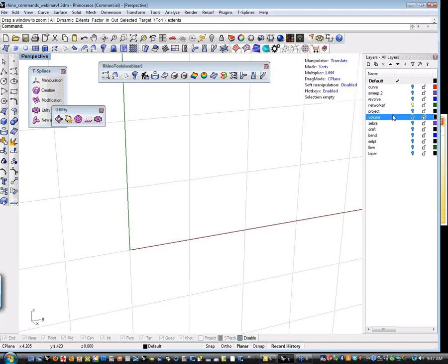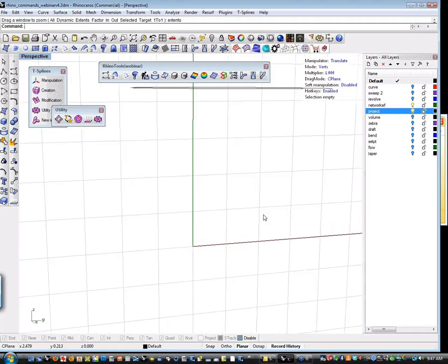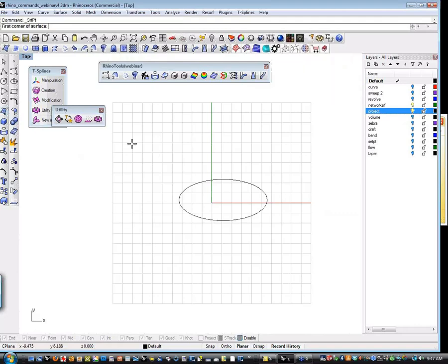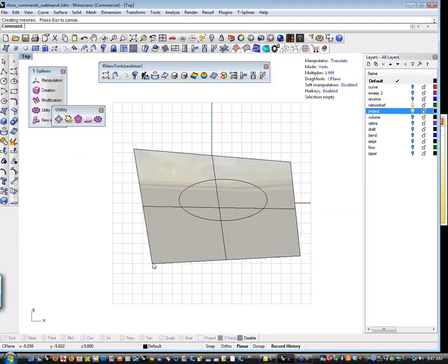Okay. Yeah, and that's the trick. If you hold down the alt key when you use the manipulator, then it will make an extrusion. And if you just move the manipulator, then it won't. So if I have a surface here, in this case I'll just make a quick 4-point surface, convert it to T-Splines.